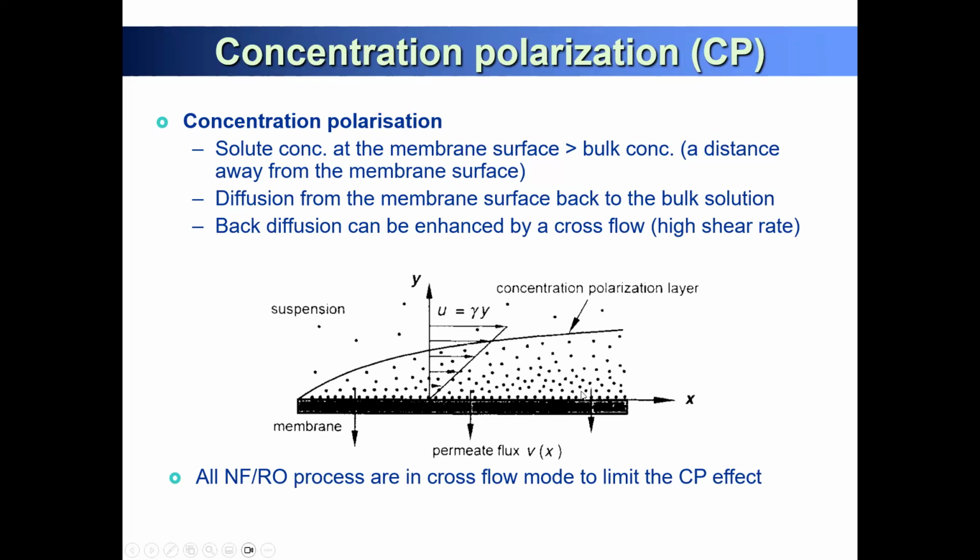So in a theoretical calculation versus the real application, you have to calculate the concentration polarization and the osmotic pressure on the surface of the membrane to see the real osmotic pressure. You have a permeate, you have a membrane, and your seawater concentration is 3.5% here.